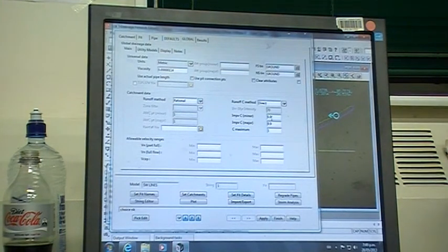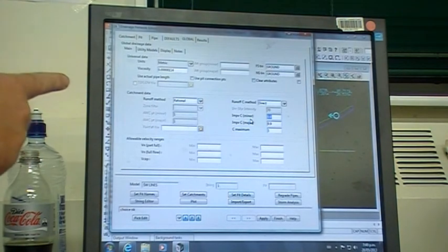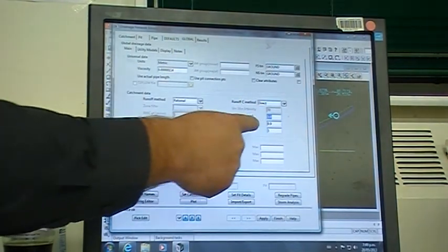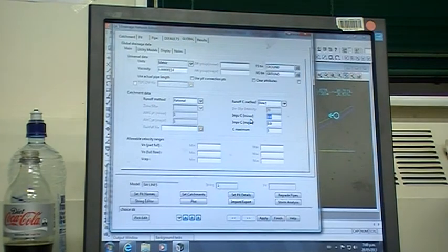We can preset things like our impervious levels, the defaults, with a C maximum of 1. What I would do for this assignment, to make sure that you don't have problems, because we are only setting one C value, is that whenever it asks you for it in the defaults, just so you don't get it wrong, set that to 0.65.